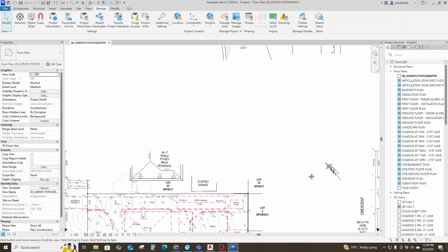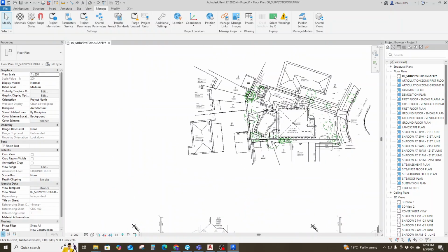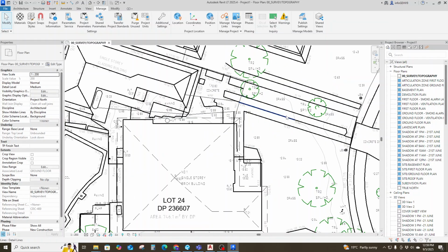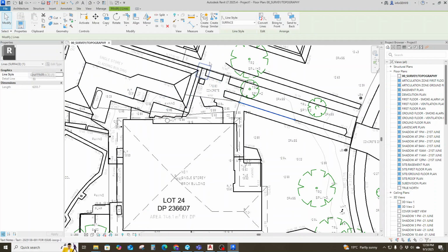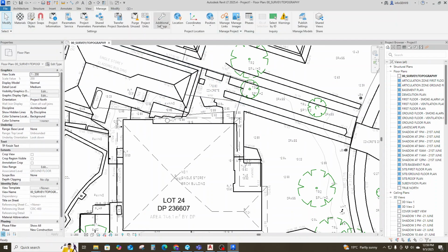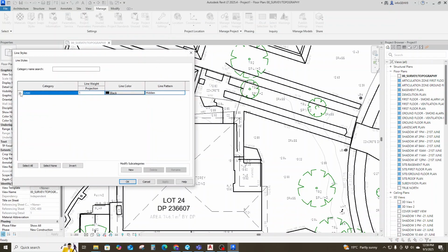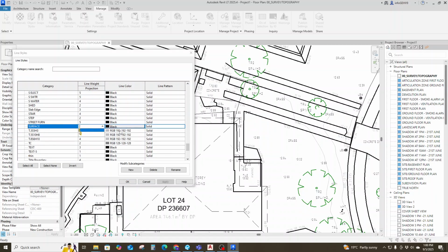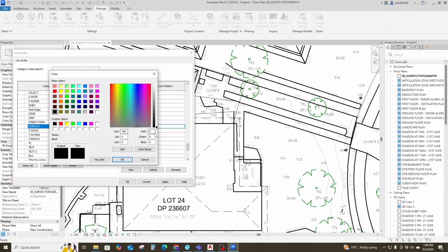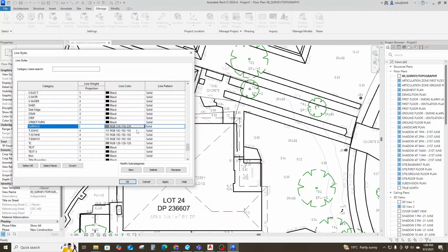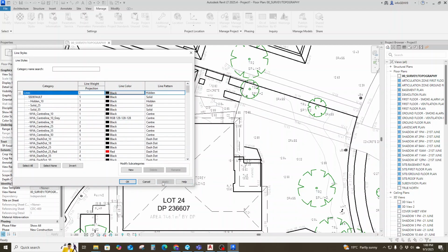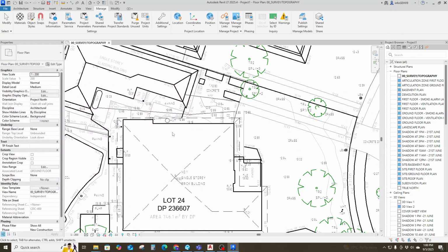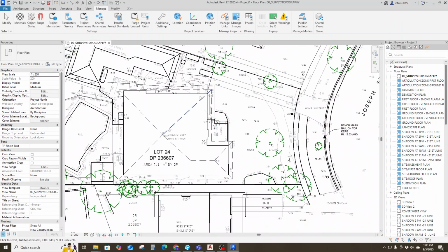Now we'll go here and recheck what the name of the layer is. It's surface. So we go here, additional setting, line styles, and we say surface. We make this 2, and this one we make 128. We say apply, and you can see the lines are getting better. The surface is getting cleaner and better.